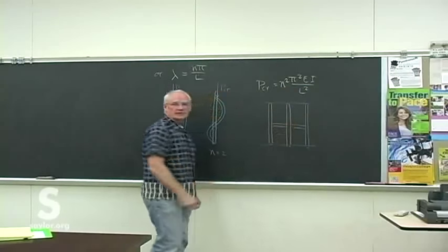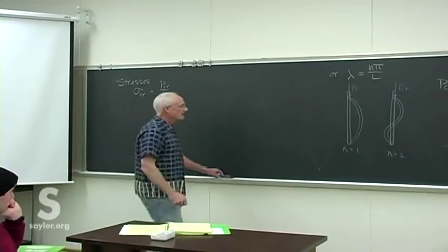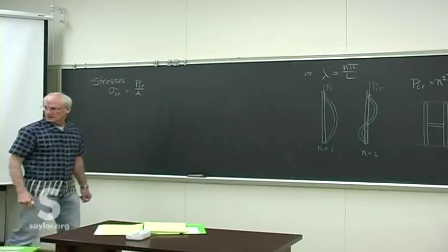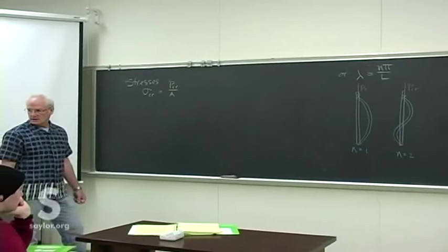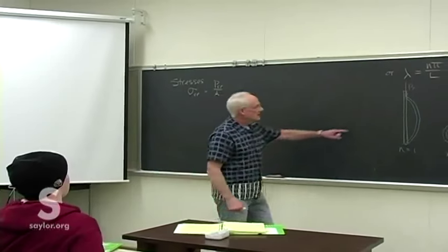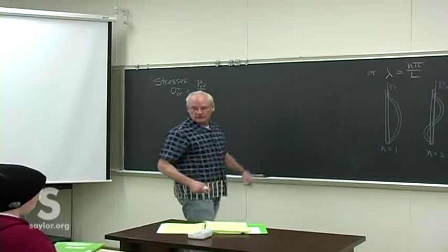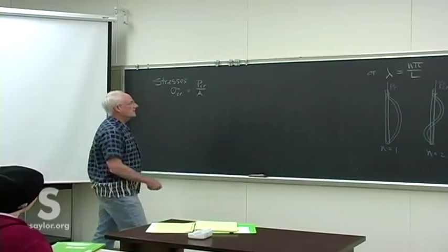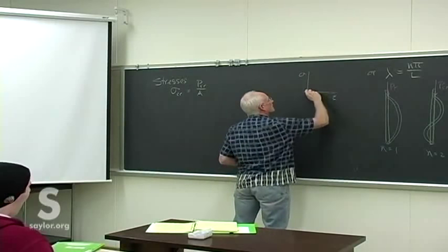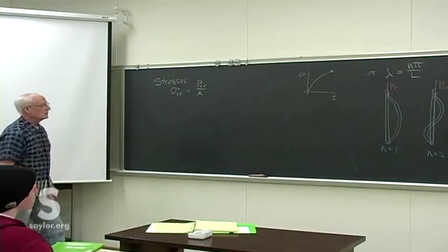So there are typically stringers put in there. But if you pour concrete around these, then they're not really columns anymore. Yeah. But the column itself made out of concrete? Yeah, you could, except concrete won't fail by buckling like this. Concrete will fail. Remember the stress strain diagram for concrete was something like that, it's good in compression, and then it just fails. It doesn't go through very much bending.